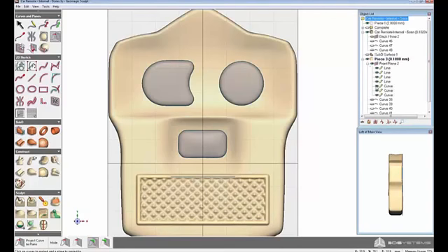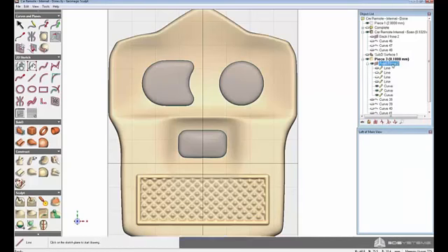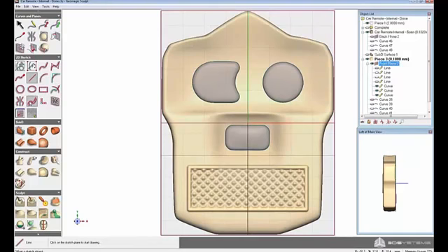But of course, if I were to do that, I would expect that the buttons would fit perfectly with the innards. Of course, that's not going to happen. I need some clearance, right? Now watch how easy it is for me to go ahead and do an offset. So come back here, do the sketch, click on the offset button, and I'm going to select that. Let's do a distance of maybe 1/4 millimeter offset. Right?